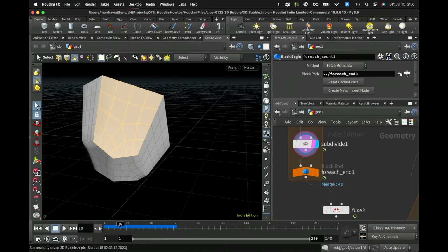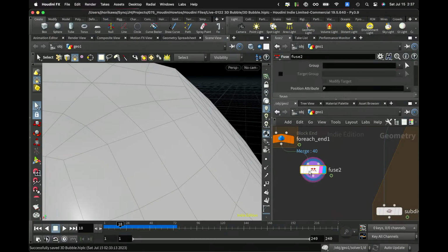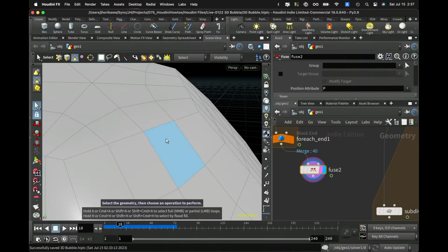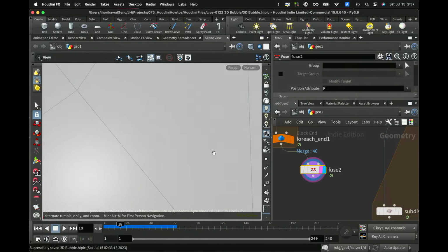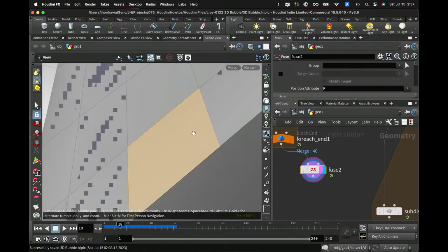So let's do that. To do that, what I could do is to try to have a single-sided geometry out of this output. Meaning if you have a duplicated surface, for example on the inner surface, you currently have a duplicated surface in and out like these.